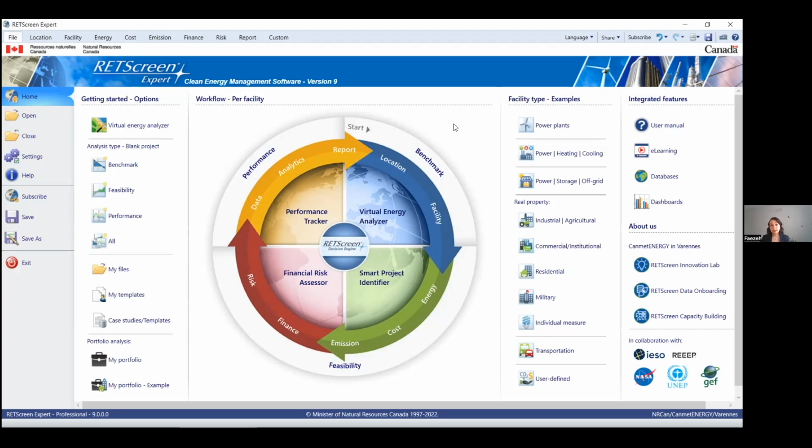Third, they will check if we need to reduce more GHG emission to reach the target of 90%. If we need more, the archetype will calculate for you the amount of on-site renewables, such as, for example, the photovoltaic system that you need to install to reach the 90% goal for the GHG emission reduction. One more thing that the archetype checks is the amount of electricity consumption in the proposed case. So why does it do that? It's because when you electrify your heating system, it means that you are increasing the amount of electricity consumption of your building.